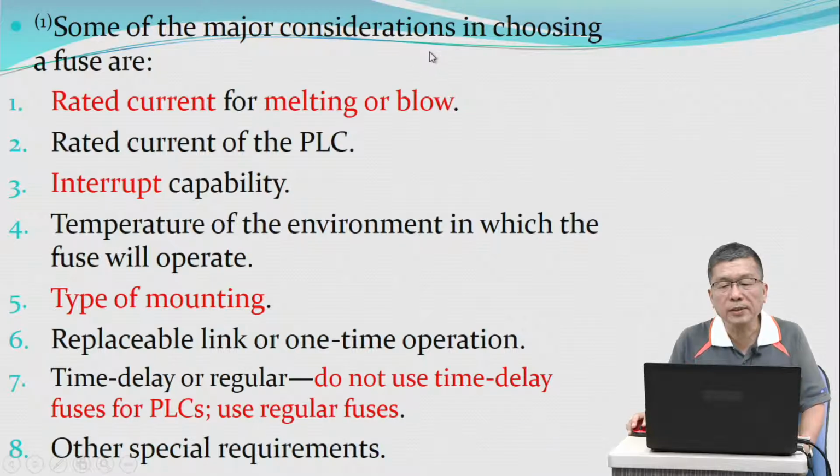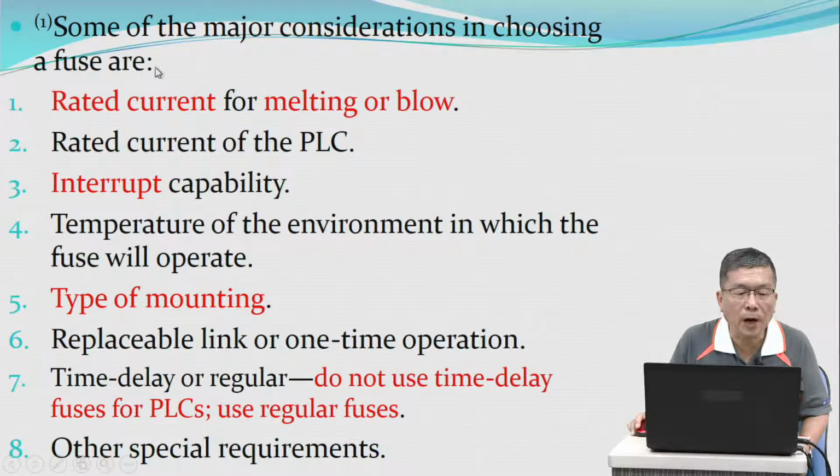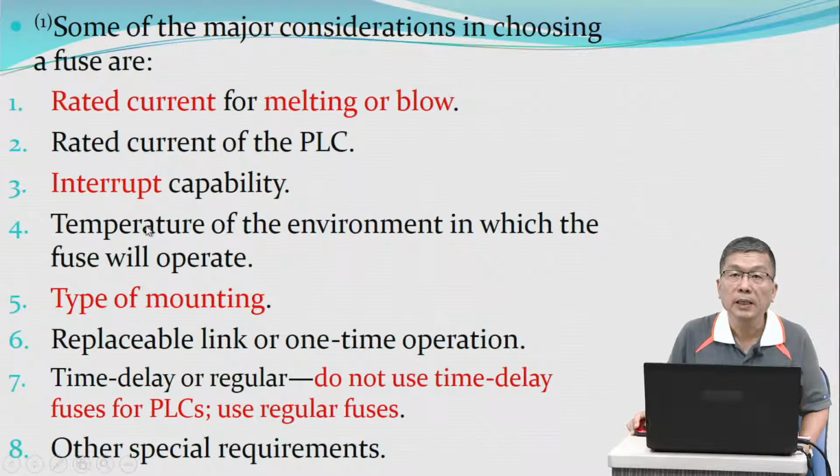Some of the major considerations in choosing a fuse are: rated current for melting or blow, rated current of the PLC, interrupt capability, temperature of the environment in which the fuse will operate, type of mounting, replaceable link or one-time operation, time delay or regular.